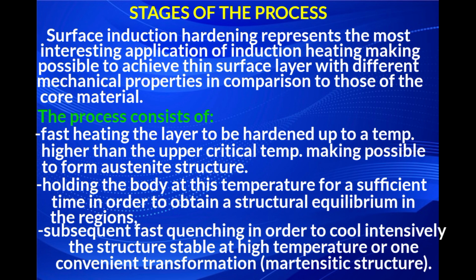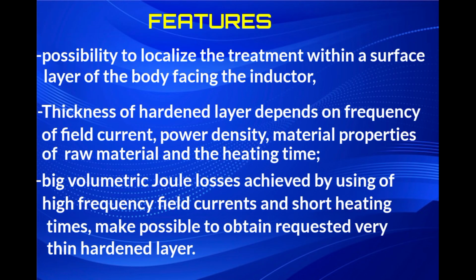Second one, holding the body at this temperature for a sufficient time in order to obtain a structural equilibrium in that region. Subsequently, fast quenching in order to cool intensively the structure that is stable at high temperature, to obtain a convenient transformation, that is nothing but martensite structure.